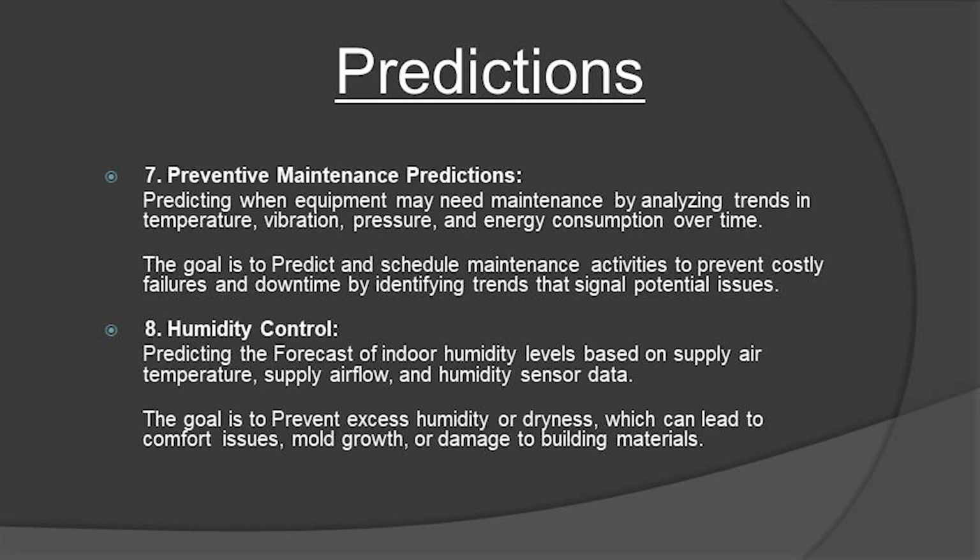Humidity control. Predicting the forecast of indoor humidity levels based on supply air temperature, supply airflow, and humidity sensor data. The goal is to prevent excess humidity or dryness, which can lead to comfort issues, mold growth, or damage to building materials.